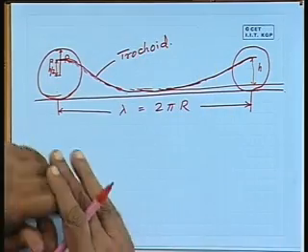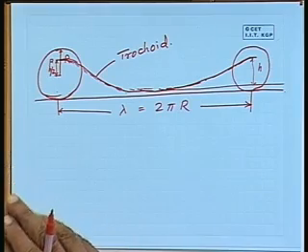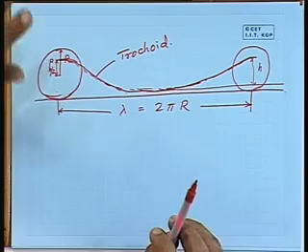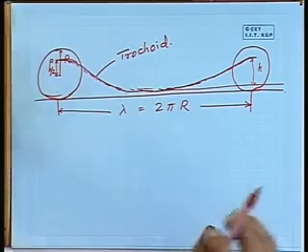So now we are in a position to define a curve which we can consider as the wave profile and is mathematically acceptable to us. Okay. So now once we have this trochoid, then we consider the ship to be poised on a trochoidal wave and then try to find out what is the buoyancy and what draft position it is going to attain to give you that buoyancy which is required to balance the weight of the vessel. This is what we try to do.